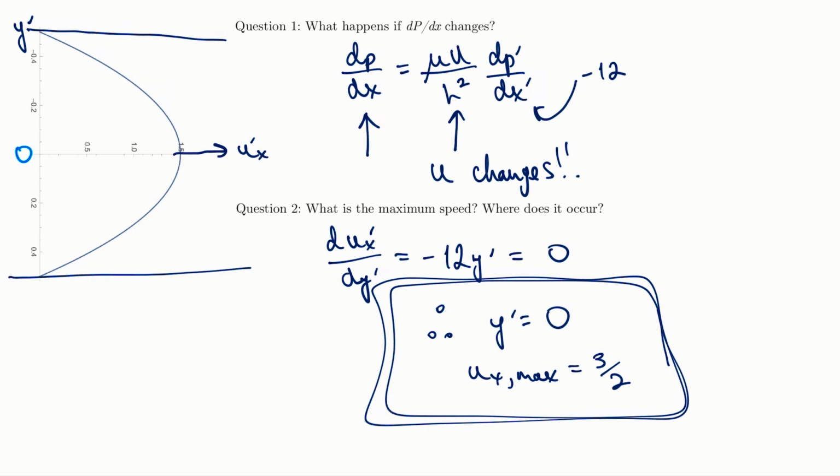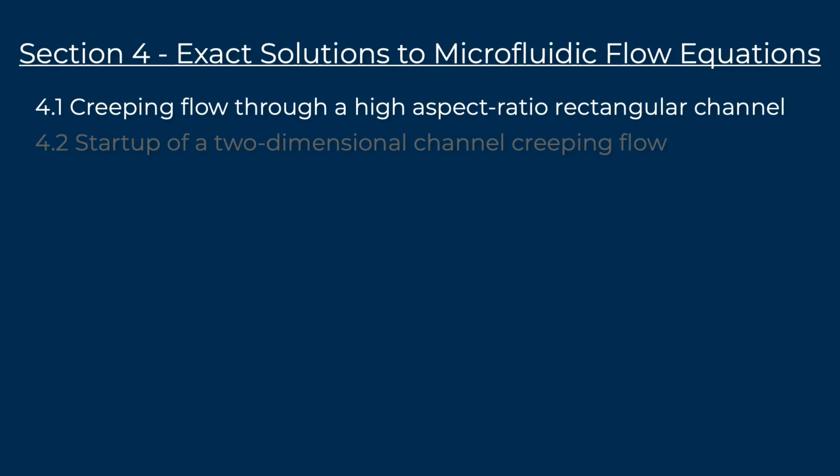So that's an exact solution to flow through microchannels. Awesome, right? And we can see this process of simplifications is applicable to a lot of fields. Just to summarize, we took our equations from before, simplified them with our dimensional analysis, which we derived in the last lecture, and ended up with our Stokes equation. Then we took our geometry of a microchannel, since flow in microfluidics occurs through these channels. We applied our boundary conditions, went through the whole solution, simplified our equation as much as we could, and got our final velocity profile for flows in microchannels. Okay, and that's all for video number 5. Thanks for watching.